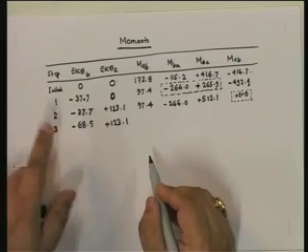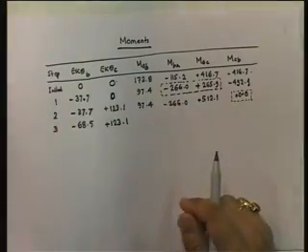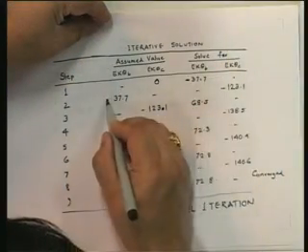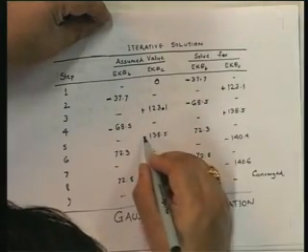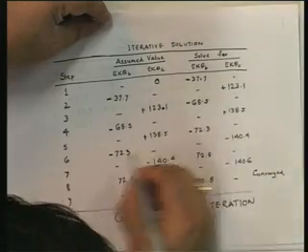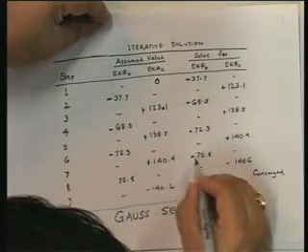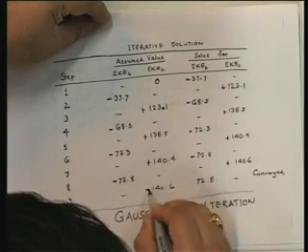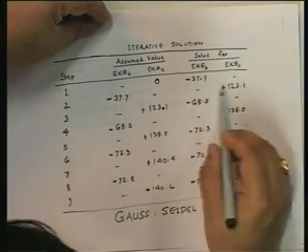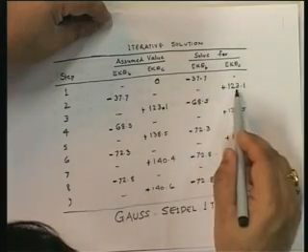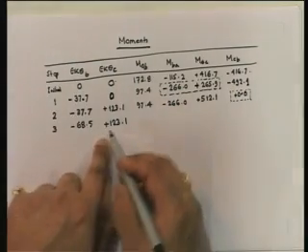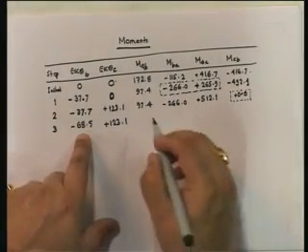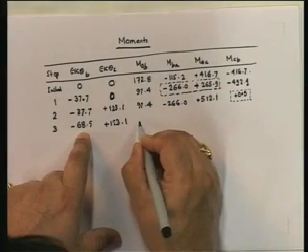Note that these are exactly the numbers that I had over here, except that I made one mistake. I took clockwise as positive, so this is anti-clockwise. My anti-clockwise is positive. So the first step was this, the second step was this, the third step is 123 minus 68.5, that's what I have over here. I've clamped it here and released it here. When I've released it here, what does my value become?